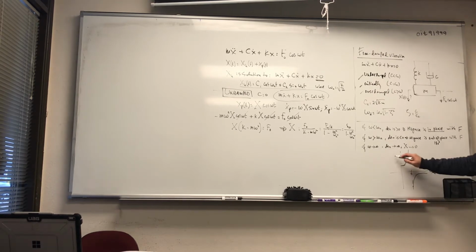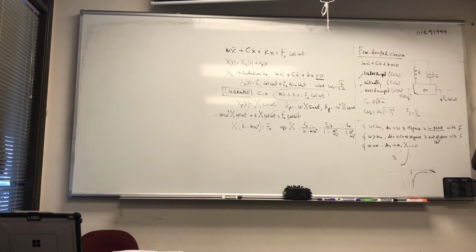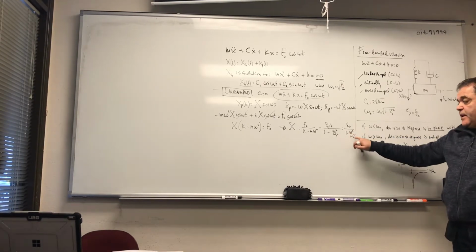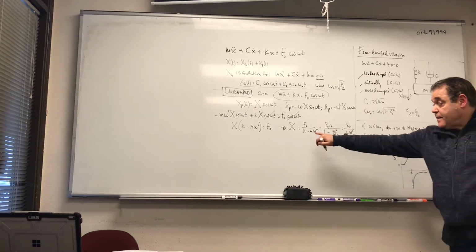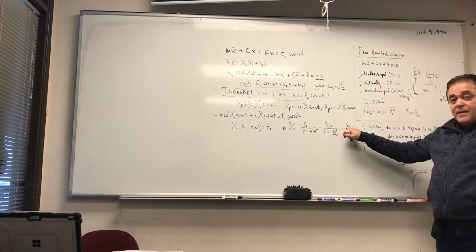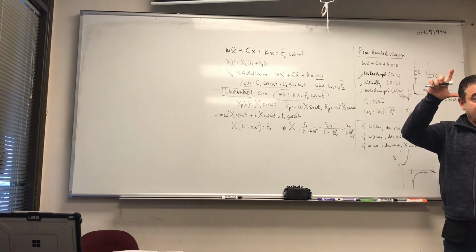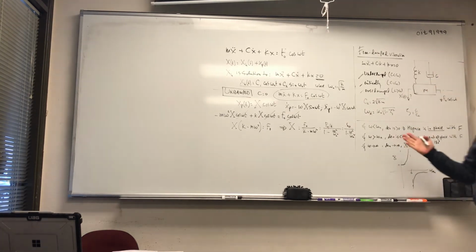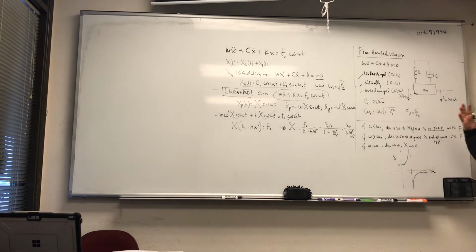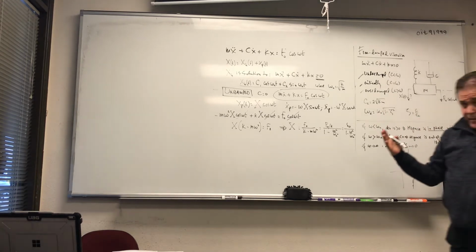And this is x. See how the amplitude, and this is 1, obviously, because when omega is equal to 0, the denominator is equal to 1. That means that the amplitude will equal the static deflection. Okay, so that's kind of the big idea behind this chapter.